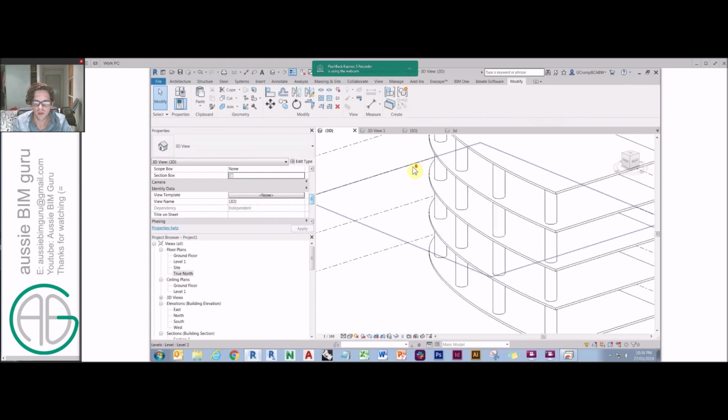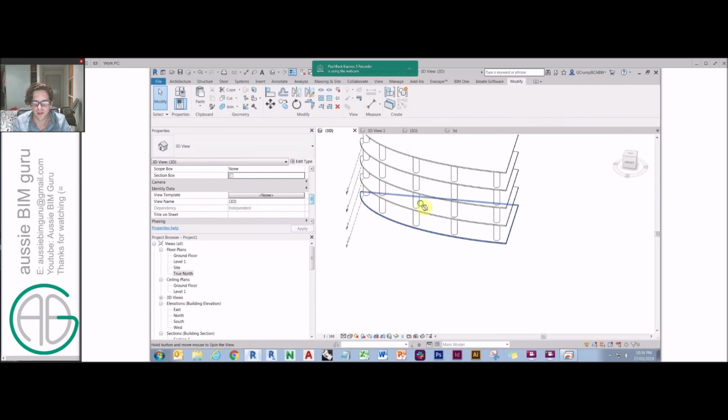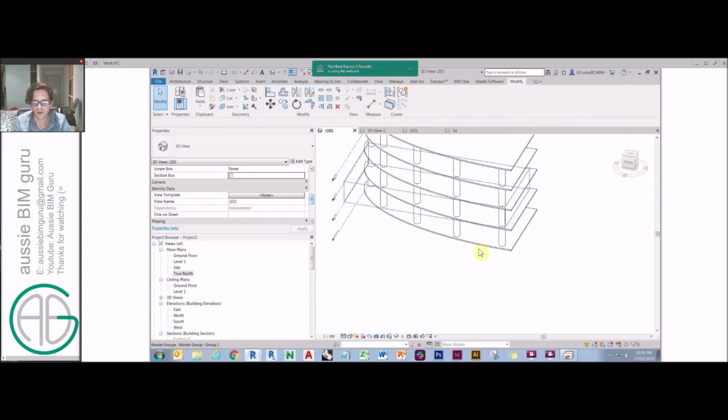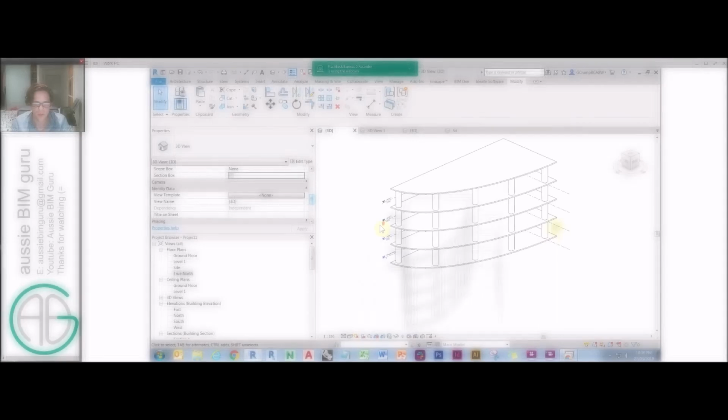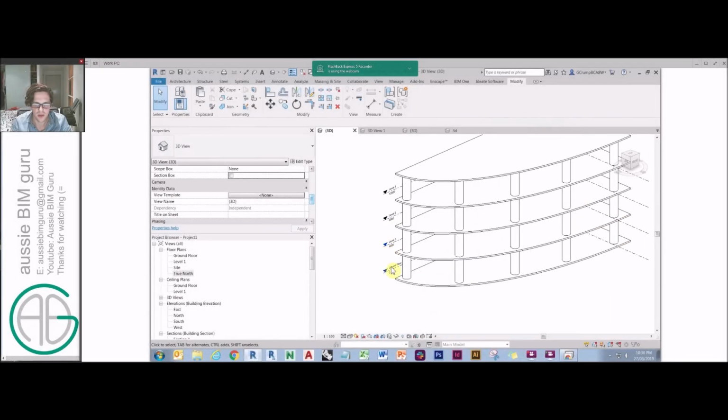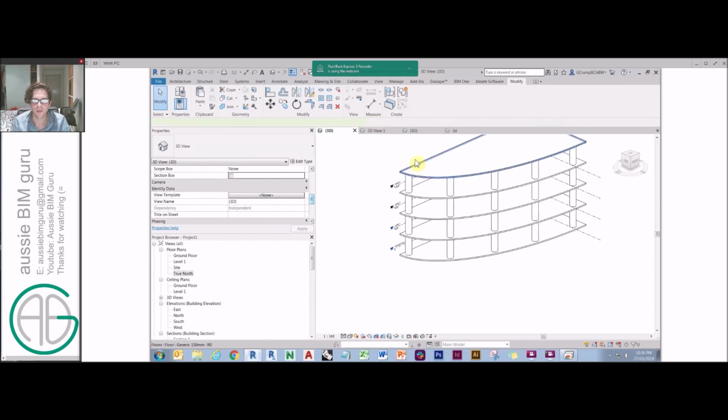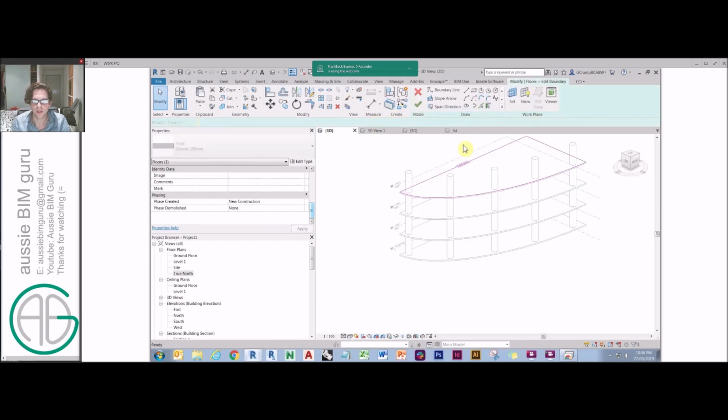In this case, we've got a scenario where we're trying to clad a zone here to do a solar study. It's on a curve, just because I thought I might do something a little bit more complicated than a rectangle. Each floor is spaced by 4 meters, so we have 1, 2, 3, 4 floors. We're going to replicate this in a conceptual massing environment. We have an elliptical floor plate here to generate our curve, with one side at 15 meters and the other at 32.